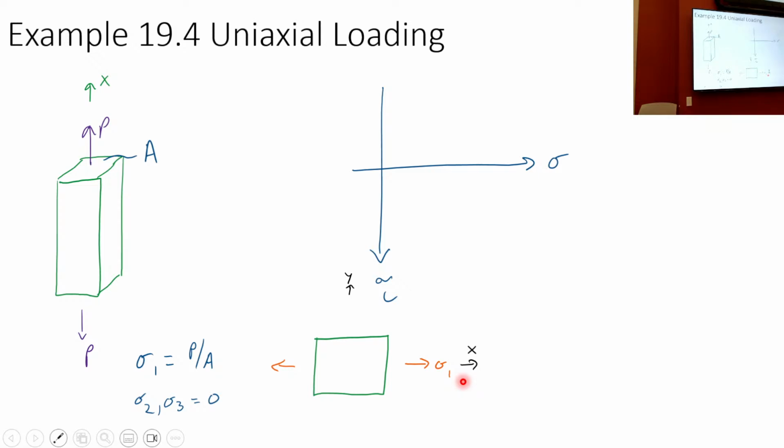I got one point that I'll say has some value, right? On the x-axis. That would be sigma 1, right? That's P over A. Where's the other, sigma 2? No, so sigma y, what is sigma y here? It's 0, right? So where is it on the sigma tau axes? Well, where can I have 0? Yeah, at the origin, right?